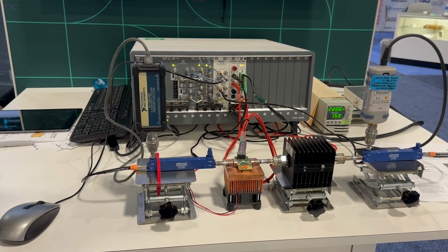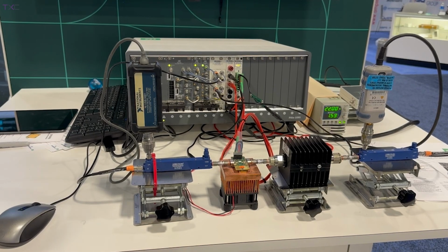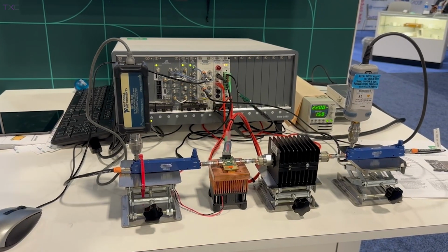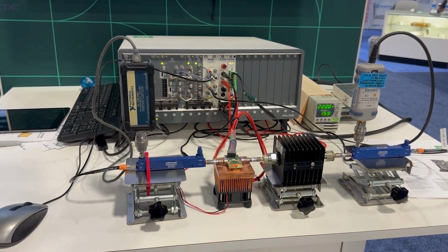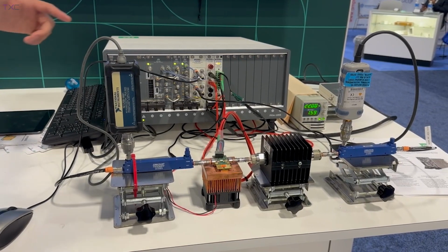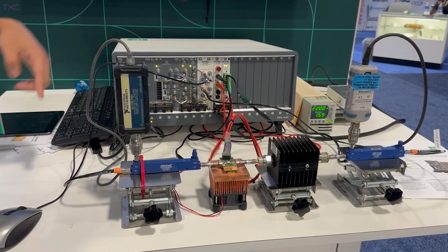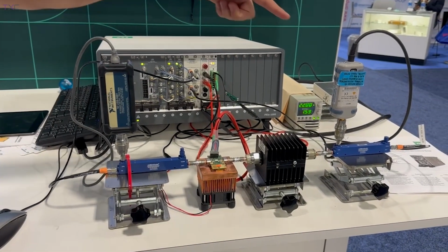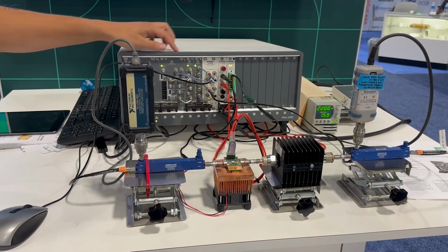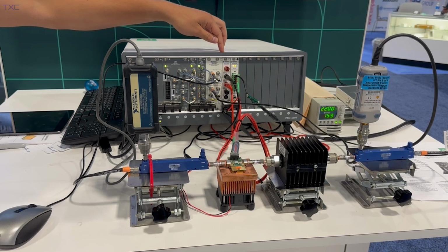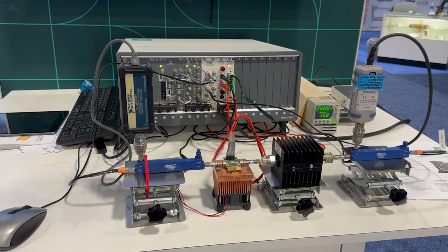So this particular setup is intended to be a validation bench for any user looking to validate the performance and characterize power amplifiers, RF power amplifiers. So our device under test here is a high power GaN PA. We have that connected to our PXI vector signal transceiver. This is generating our RF waveform. It is sending it through the DUT. We're taking a few RF power measurements through these power meters, and then we're acquiring that RF signal back in our VST. We're also providing digital DUT control as well as DUT power through our SMU and our DMM here.